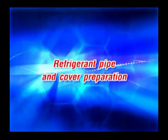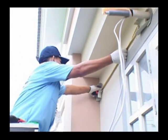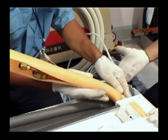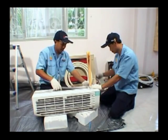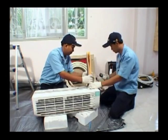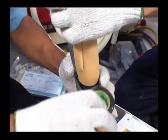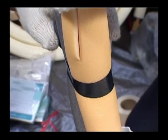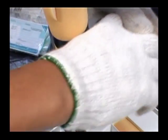The refrigerant pipes and cover preparation. Measure the suitable length of the pipe cover. Unroll the pipes that are supplied with the air conditioner. Keep the PVC pipe lower than the refrigerant pipes to facilitate drainage. Tie the pipes, the PVC pipe and the wires together with wiring tape. Then neatly wrap the piping tape around them.